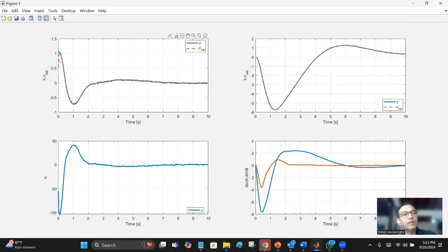Can you see that? The extended Kalman filter is able to estimate the position. This is with some noise. You can see the noise here, but the y-axis is bigger, that is why you don't see the noise so large. But it is noisy. We get accurate estimation for pole angle and cart position.